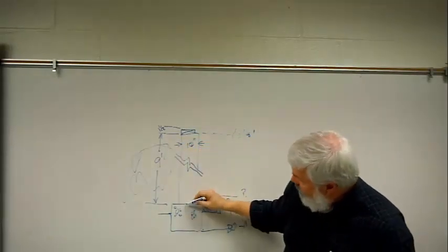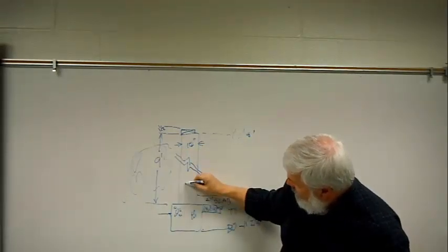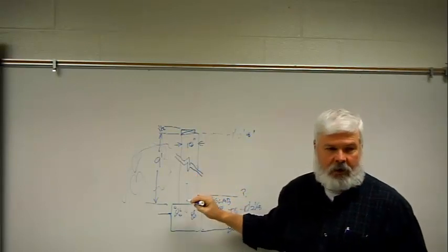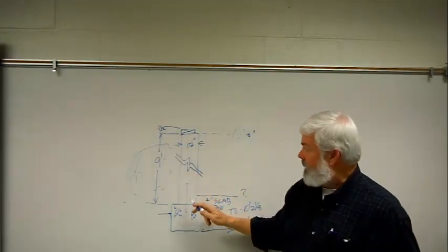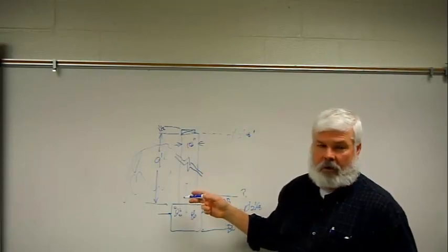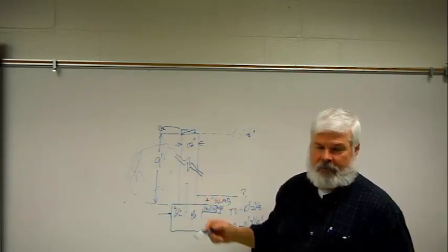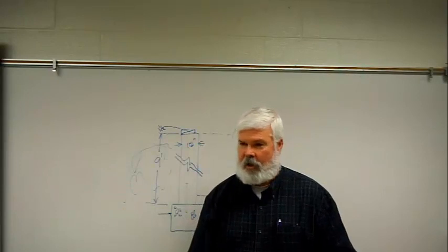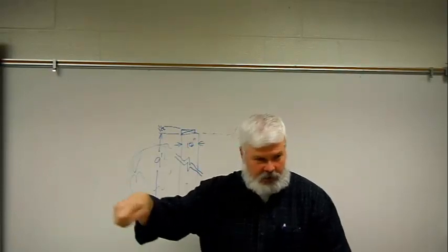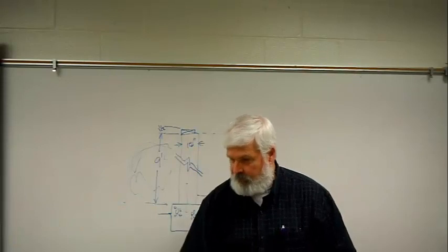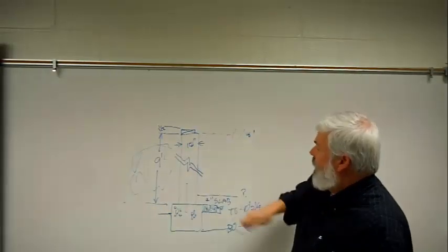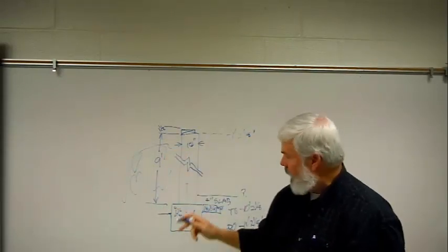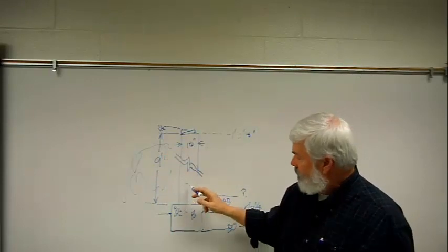So when you pour these concrete footings, what we do here in Georgia, there's other ways to do this, is we stick a piece of 3/8 inch or 1/2 inch rebar. Does anybody know how they cut rebar on a job site? They have a really big device that'll just pinch it and cut. It has like 4-foot handles on it, and you can stick the rebar in there and cut it with one whack. But anyway, the rebar is put about every 3 or 4 feet, buried down in the concrete while it's still wet.